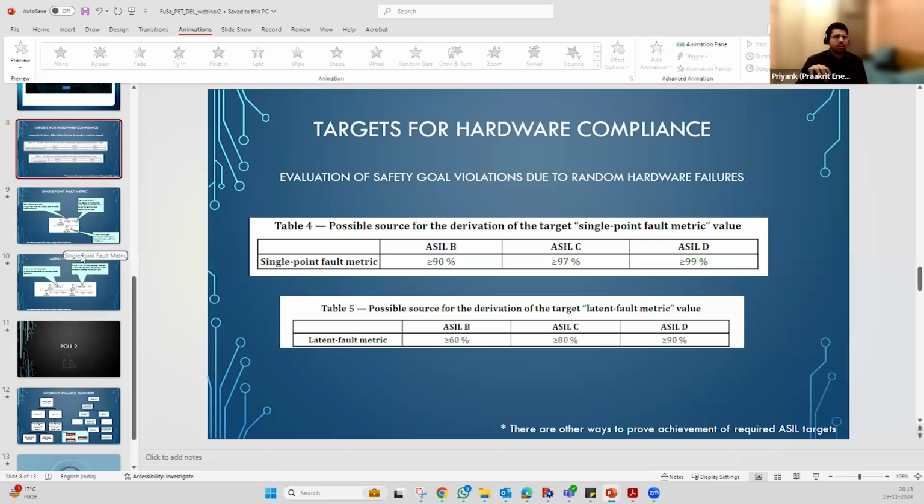Similarly, there are stringent requirements for the total failure rate as well, which is called PMHF. And it helps you take a top level safety goal at vehicle level, which is calculated at OEM level, and permeate those requirements to tier 1, tier 2, tier 3 and tier 4 suppliers as well. And that's what an FTA helps to achieve. This FTA can be done at OEM level, tier 1 level, tier 2 level, depending on the specific product.